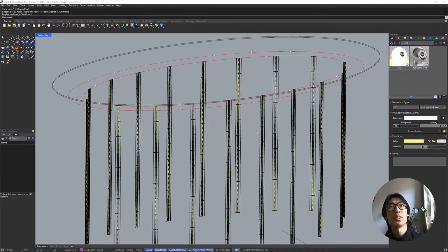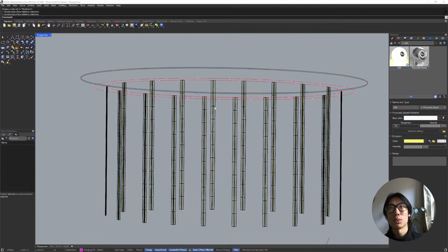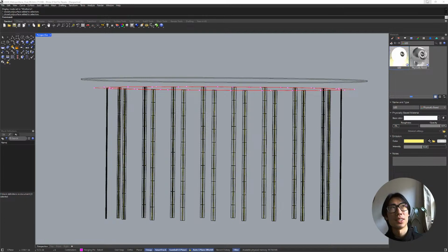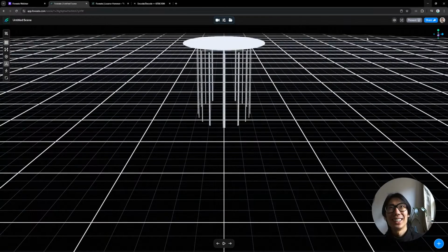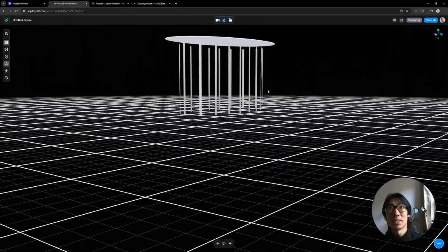This way you're not using a whole bunch of memory making unique copies of every single thing. Instancing takes one reference copy and then it updates it for everything else. What I probably should have done is created one of these lines of battens and then used blocks to instance it out 18 times, but I didn't do that. Be better than me.